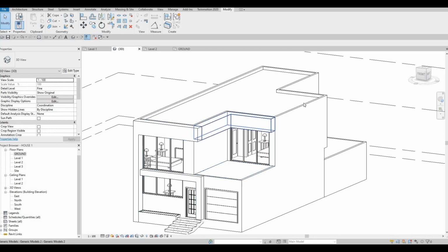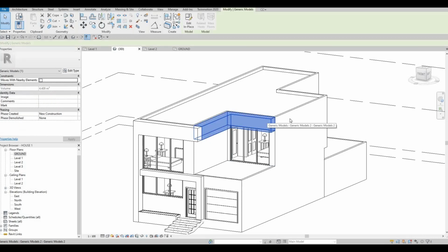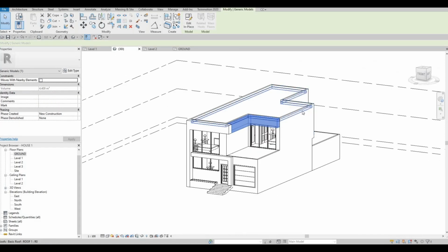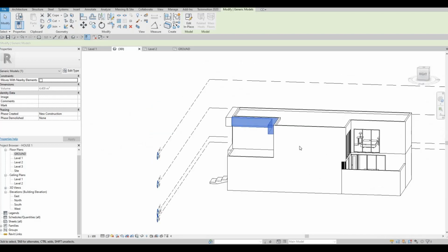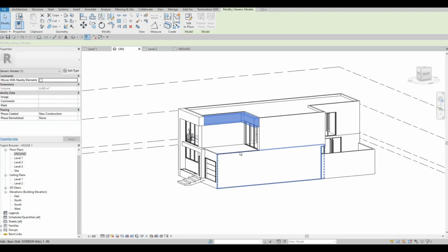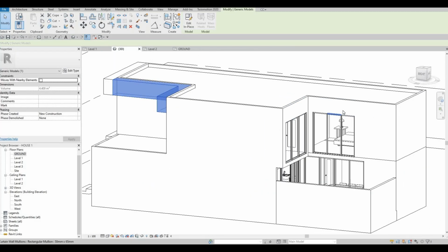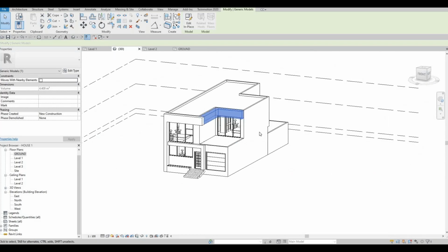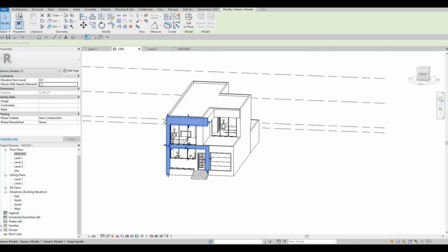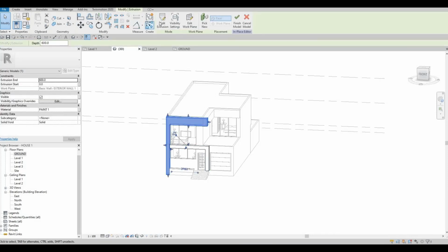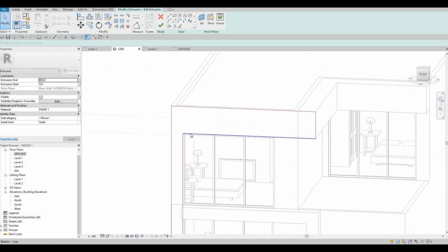What I'm planning to do is wrap around this extrusion or sweep around these walls, even in this one, so that we have some changes right here as well. We can also add some of the lights there. So what I'm planning to do is I'm going to delete this portion. So edit in place. I'm going to select that, edit extrusion. I'm only going to trim it here and trim it on this side. The rest will be deleted.